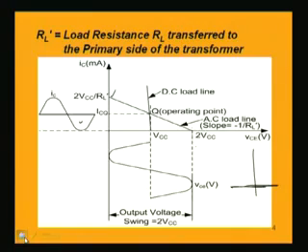Now, this operation of this amplifier, both series fed which we discussed earlier and the transformer coupled power amplifier that we discussed today, are both in class A operation, because if we look into the output characteristic, I mean the collector current, then we see that the current is flowing for the whole cycle, because it is not going down to either saturation or cutoff. So, it is in class A operation, the conduction angle is 360 degree.